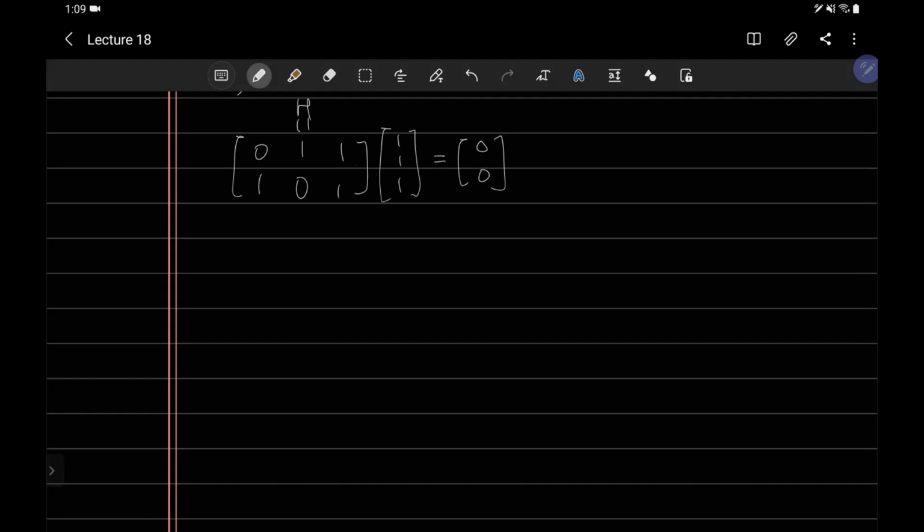Then what happens if I have some error in the transmission, like here? Now I know that there is a transmission error in the third bit. Or maybe, in the extreme case, the original code word was 0, 0, 0 but two of them are flipped. But we are not considering correcting two values, or we won't allow two bit flips.